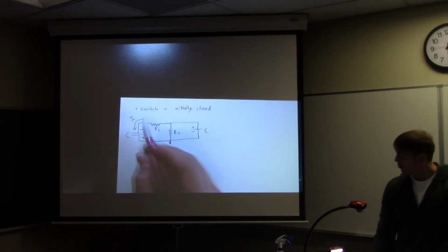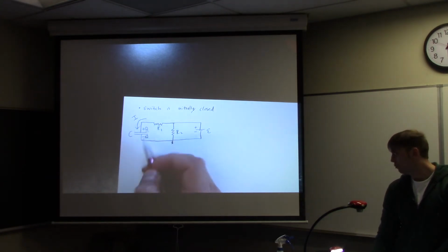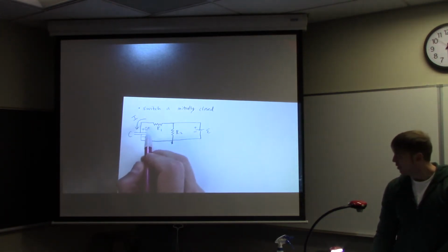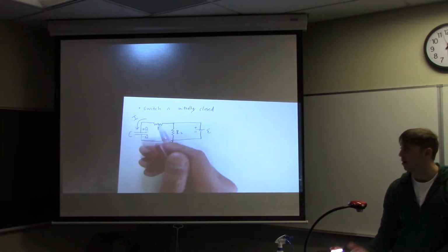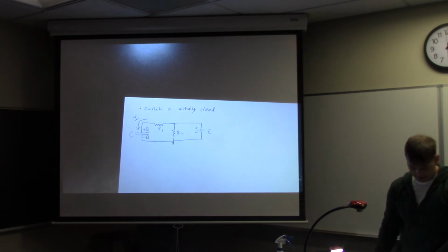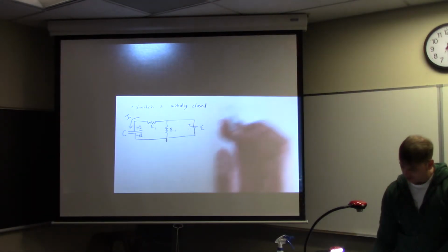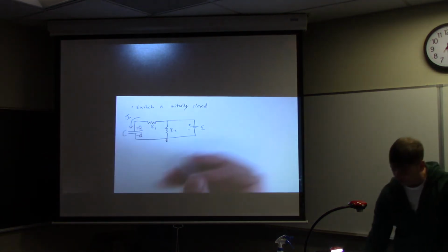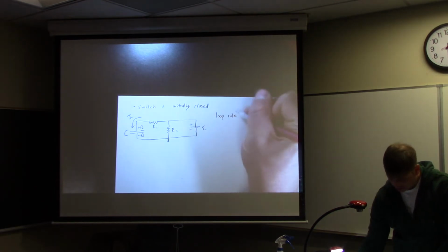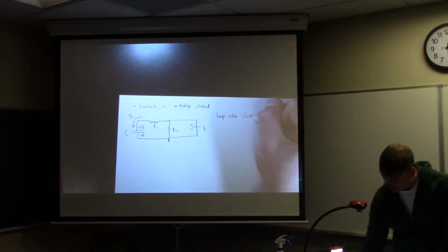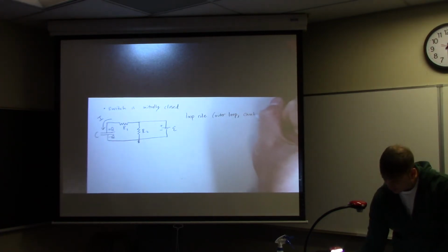How do I know the current is flowing this way? Well, remember, conventional current is telling you which way positive charge is moving. So if the top plate is acquiring a positive charge, then the current should be going towards the top plate. So that's why. All right, so what we're going to do next is kind of carefully analyze the circuit using the loop rule. And in this case, let's do the outer loop. And how about we take it counterclockwise this time?